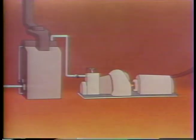The rest is lost. We can see why by examining the major components in the steam cycle. We'll consider the efficiency of each component as it affects the efficiency of the steam cycle. First of all, in the boiler, where fuel is burned to produce steam, some of the original energy in the fuel is lost up the stack as thermal energy. Typically, a well-maintained boiler is 85% efficient, which means that 15% of the original energy in the fuel is lost.